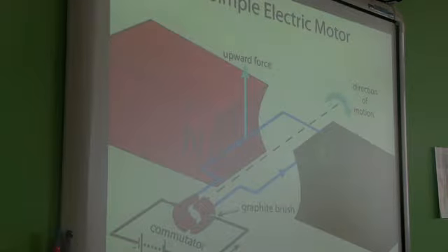When a current is passed through, the coil spins because a force acts on each side of the coil due to the motor effect. The force on one side is in the opposite direction to the force on the other side. The split ring commutator reverses the current around the coil every half turn of the coil. Because the sides also swap over each half turn, the coil is pushed in the same direction every half turn.